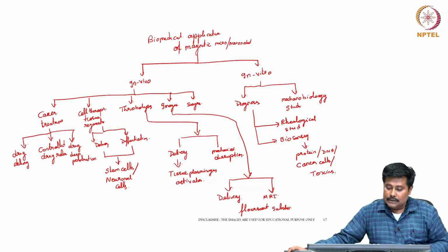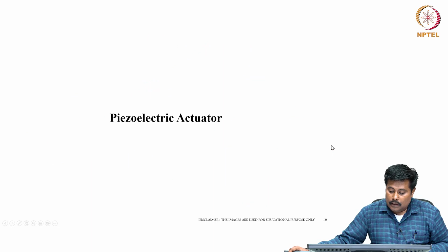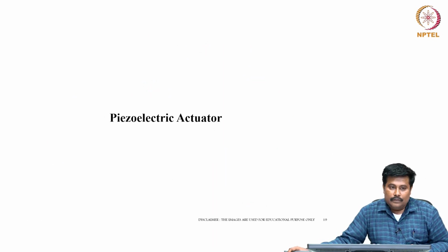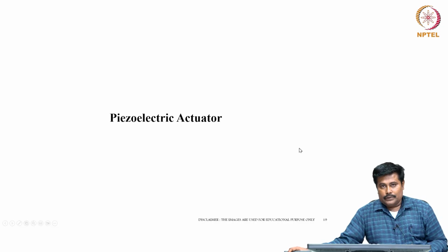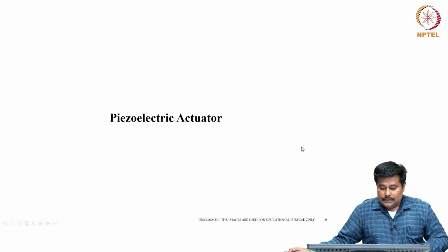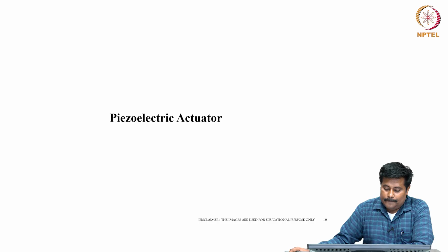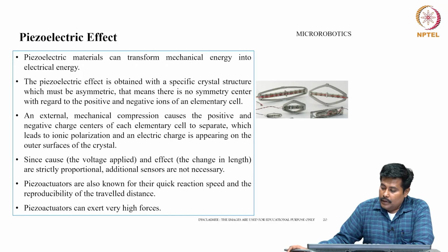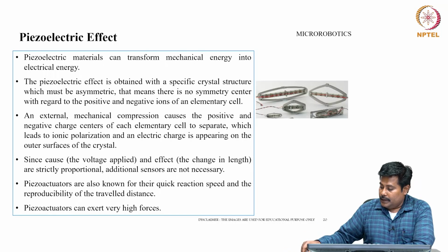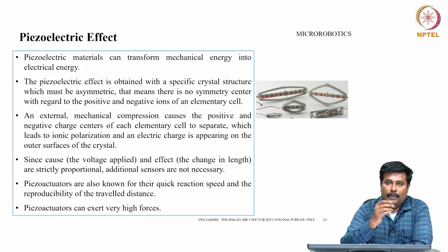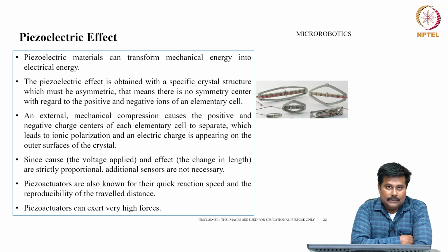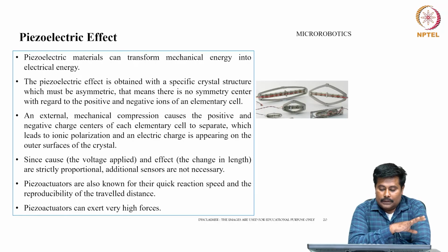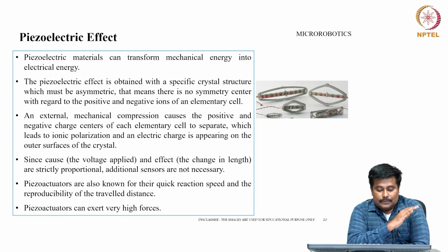Now we will discuss the next actuator, which is called a piezoelectric actuator. As far as these piezoelectric actuators are concerned, these piezoelectric materials can transform mechanical energy into electrical energy. The piezoelectric effect is obtained with a specific crystal structure which must be asymmetric, that means there is no symmetry center with regards to the positive and the negative ions.